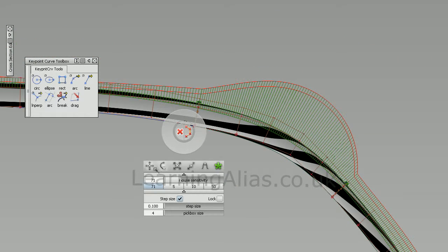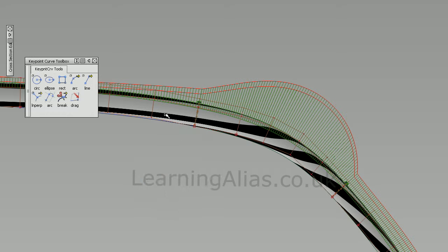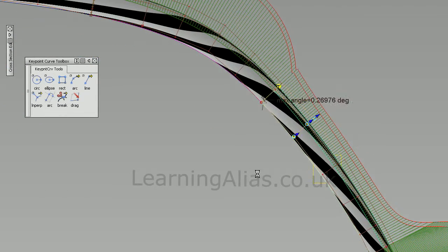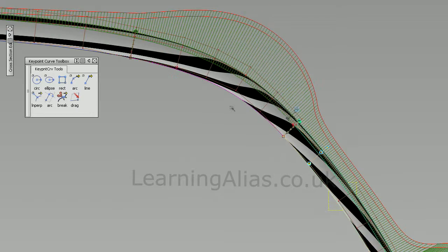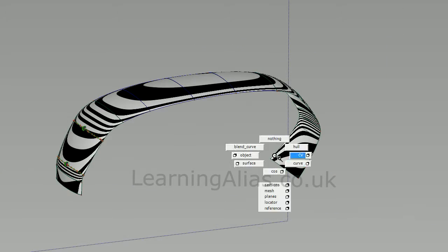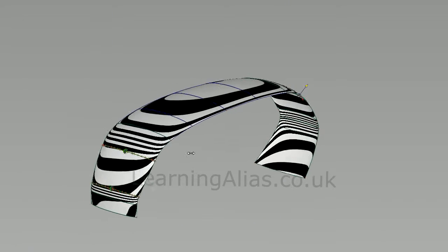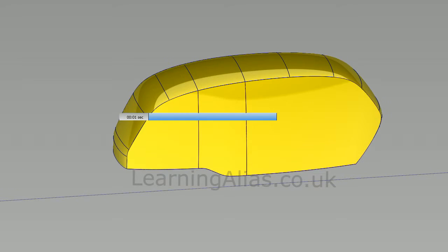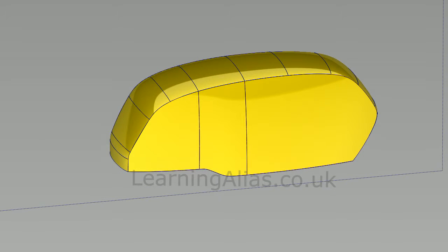And then we can delete the helper curves and transform the CVs on our parent surfaces, until our comb shows something closer to G3 continuity. And you can also slide these to increase the lead in, but then bring them down. There we are. Smooth. We can delete them, and as you can see with our diagnostic shader, I still have a bit of work to do on some of the lower rear surfaces, but I'll go ahead and do that, and then we'll jump back and inspect our reflections, looking alright.